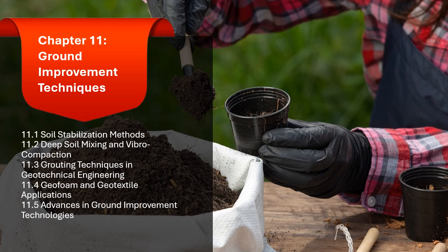1.5.2.2 Vibrocompaction advancements. Vibrocompaction is used to densify loose or granular soils, improving their bearing capacity and reducing settlement. Recent advances in vibrocompaction technologies include high-efficiency vibroflotation. The introduction of high-efficiency vibroflotation equipment has improved compaction depth and reduced energy consumption, making it possible to treat deeper layers of soil with fewer resources.